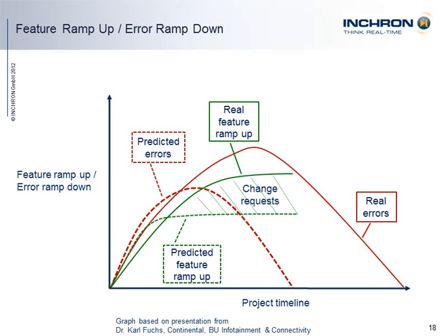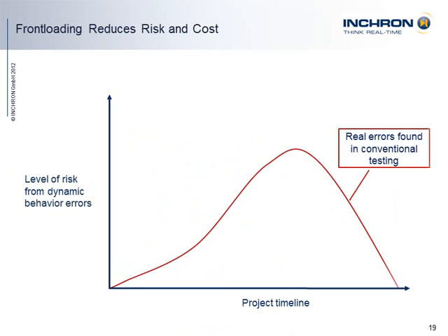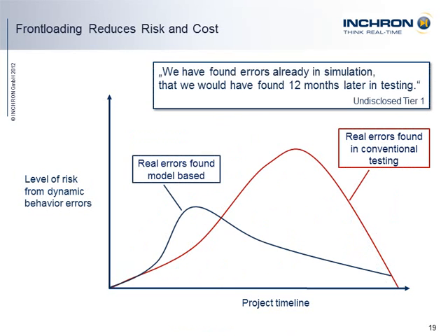His curves show all error types, including the real-time errors. For real-time errors, it's not the total number of errors that count. Often, a single real-time error is already a showstopper. For example, what if the redundant calculation for an ASLC function calculates with data of different age because of the clock drift between function calculation and redundant calculation?